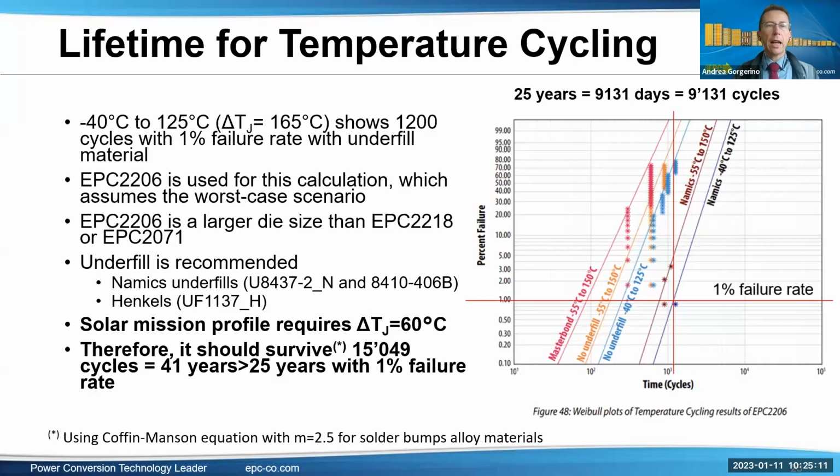So the last lifetime failure mechanism we want to look at is temperature cycling. This is where it's more similar, I would say, to silicon devices. In the end, it's a thermomechanical type of failure. Our standard testing does temp cycling between -40 and 125 degrees C.